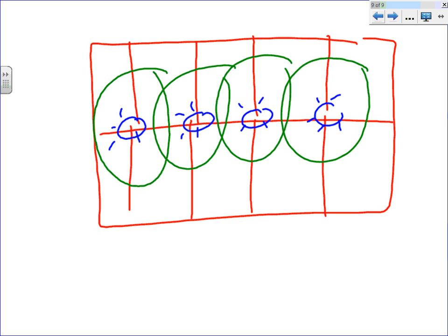The only thing I want, and this is an example in your book too, let's assume that every one of these green circles around it, right at this point here, is 0.5 foot candle. And right at this point here, it's 0.5 foot candle. Can anybody tell me what the value is at this point here, that mixture of both of them?